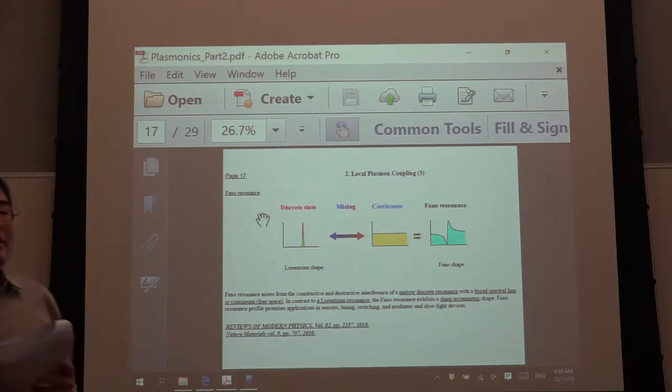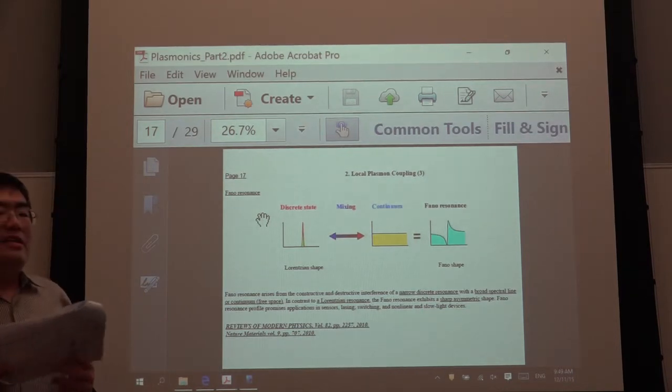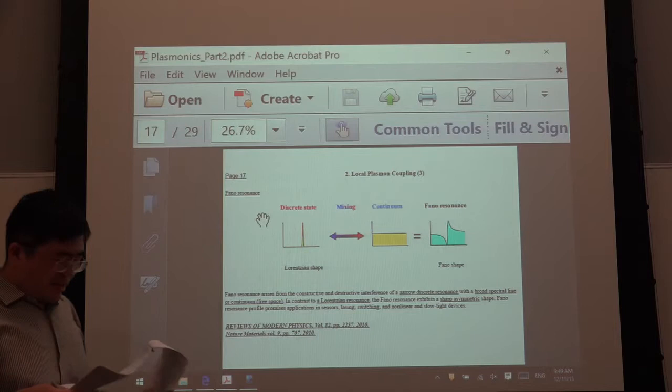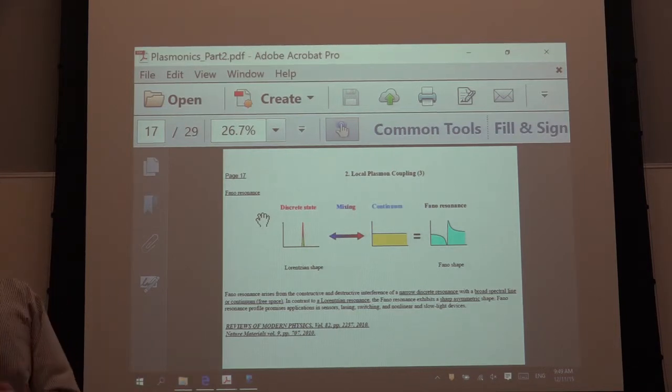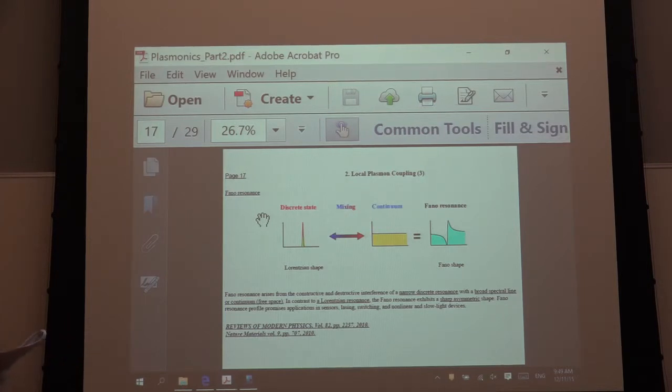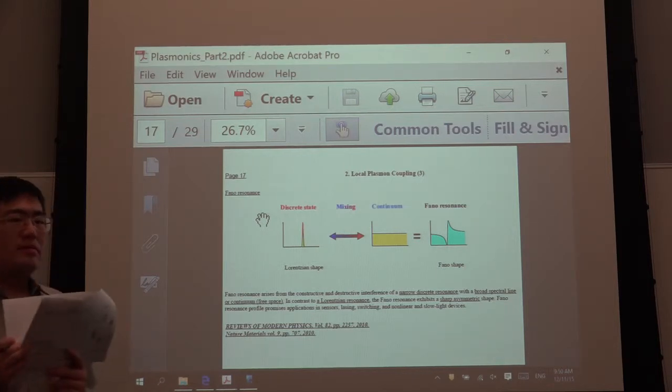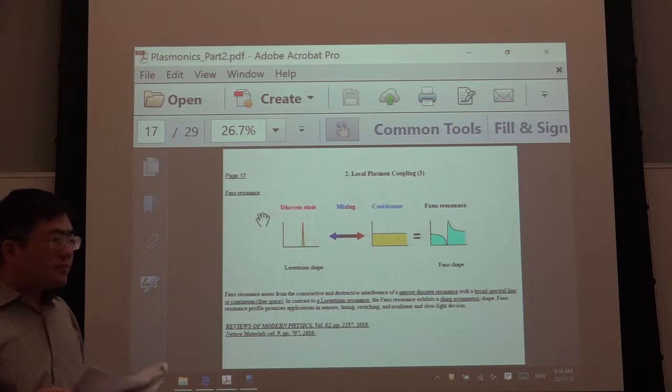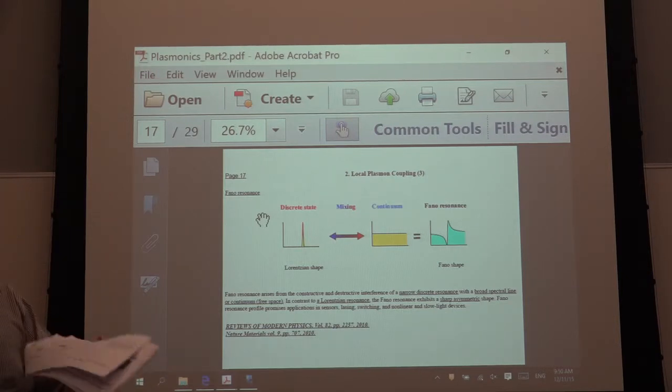Yes, in microwave, the possibility exists a lot in filter theory. You may create this a lot. We call it transmission zero. The transmission zero is due to the two-mode interaction. And actually, you could control and generate high-order zeros on both sides of the resonance. It could be wideband, could be narrowband, depending on how you control it.